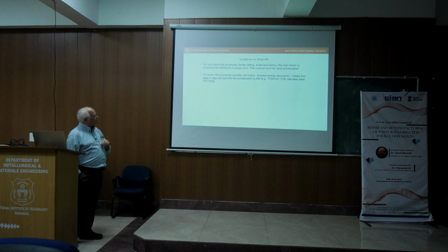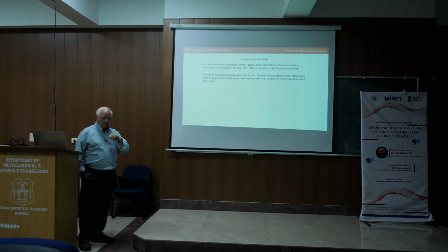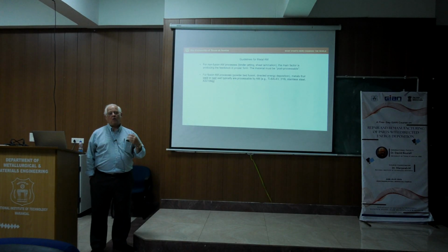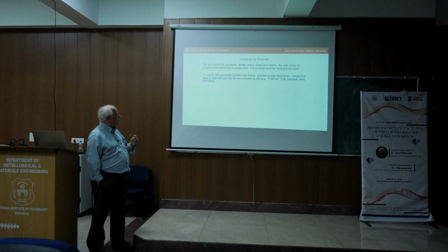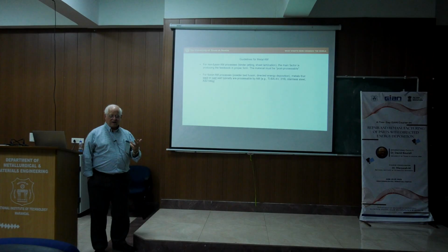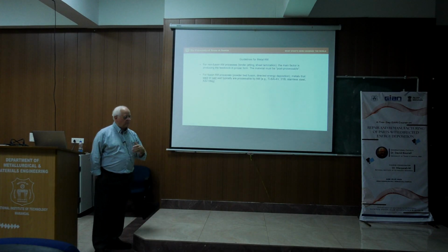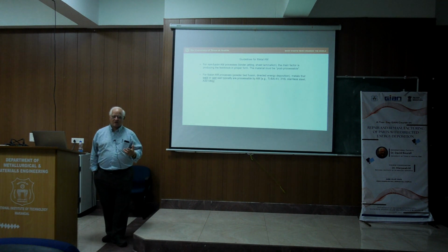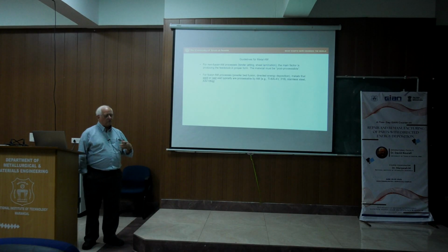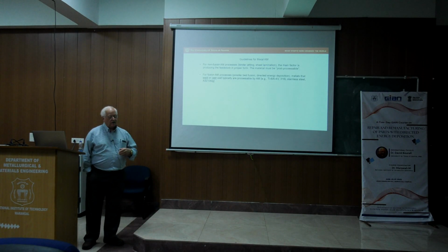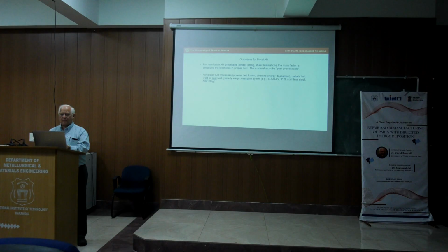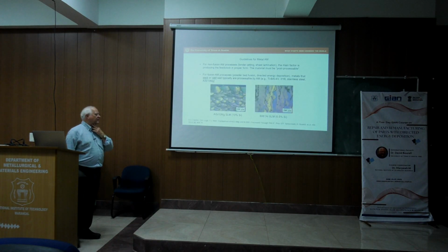However, for fusion processes, powder bed and directed energy deposition, what's been determined, just as a rule of thumb, is that if the metal will weld well or will cast well, then typically it can be processed well in additive manufacturing. And so when we look at the metal systems that can be processed well by additive, what we find is that they're also readily weldable and readily castable. Again, that's just a broad general rule.